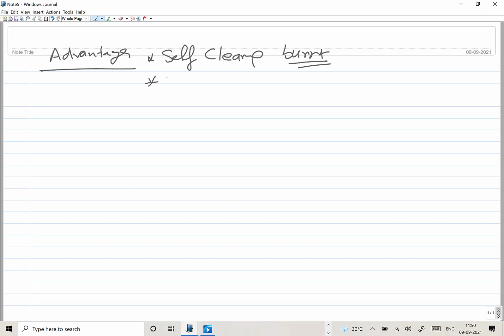So self-cleaning is one of the good features of friction welding. The second thing is, you see there is no fusion. Okay, so the possibility for intermixing is very limited. Intermixing is limited, and because of this, you find some scope for developing dissimilar metal joining. So the scope and opportunities are much better in friction welding for dissimilar metal joining as compared to fusion